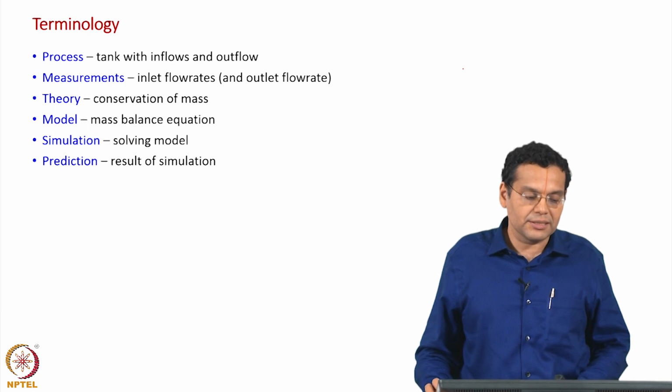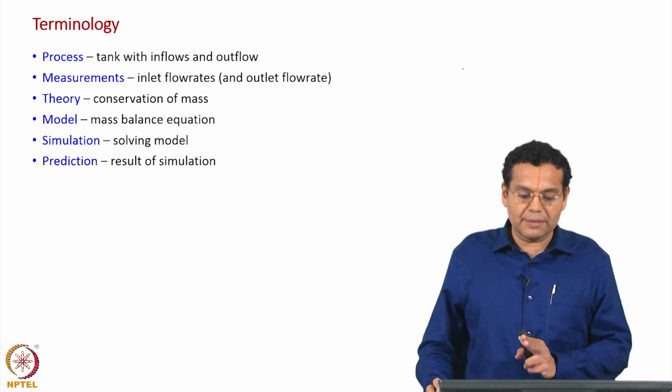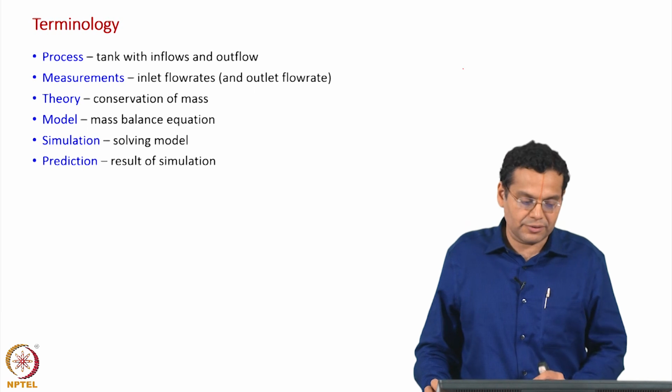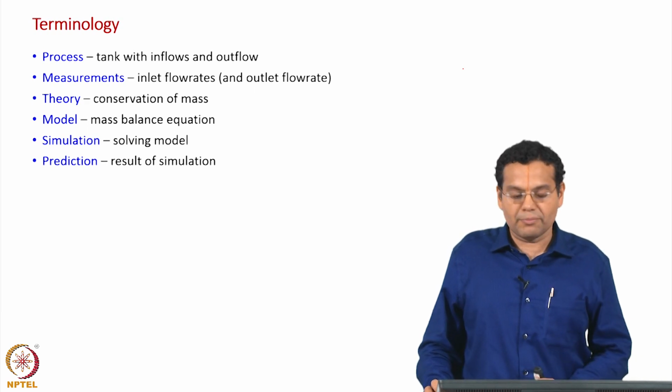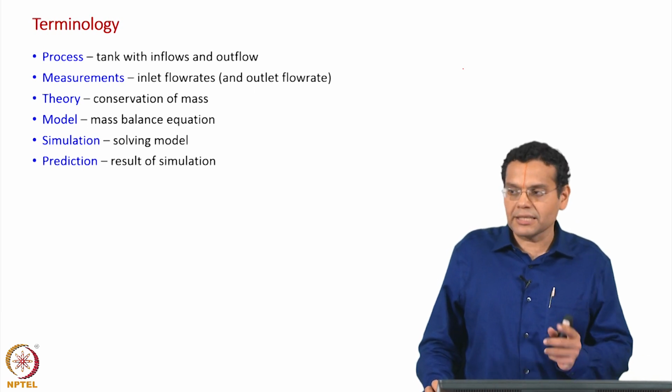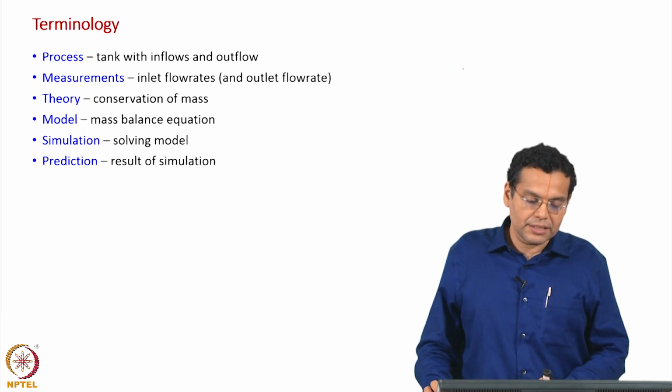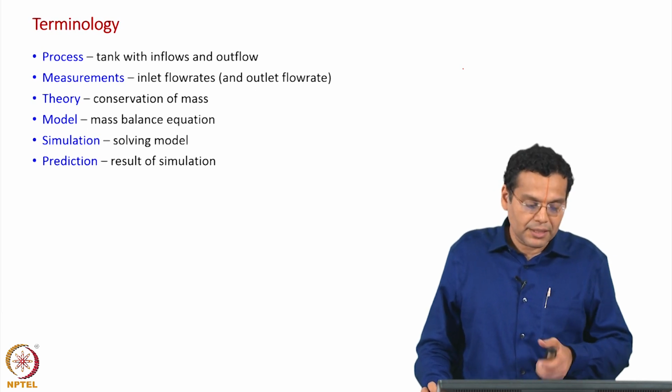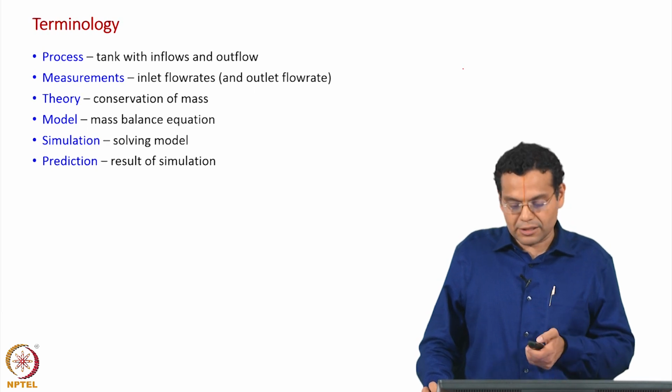So, it is process, the tank; the measurements, the two or three measurements which are taken; theory, the conservation of mass; the model is a mass balance equation; and simulation, the solution of the model, solving the model; prediction is the final result, that is the result of simulation. Okay.